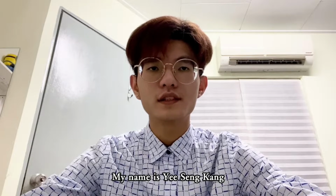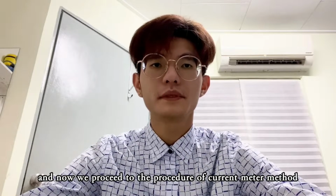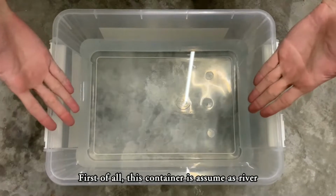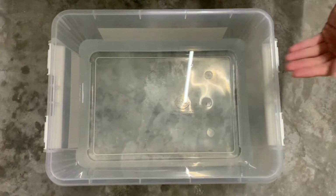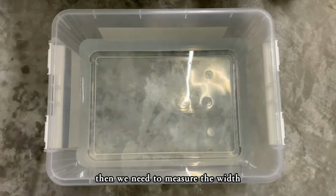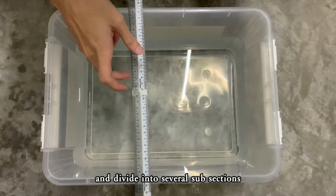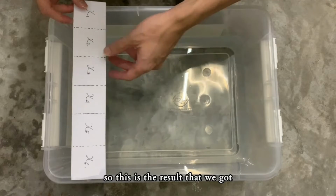My name is Yi Seng Kang, and now we proceed to the procedure of the current meter method. First of all, this container is assumed as a river. Then, indicate this is the inflow, while this is the outflow. Then, we need to measure the width of the stream using a measuring tape and divide it into several subsections. So, this is the result that we got.